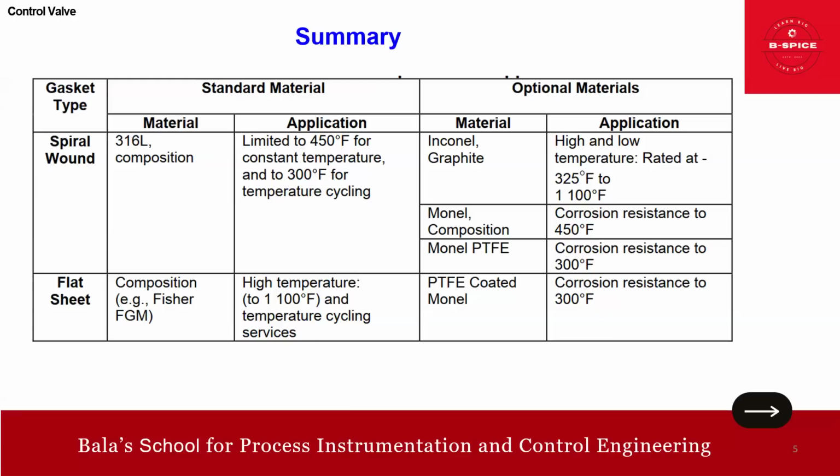But the problem is they will not provide the required corrosion resistance. So options such as PTFE coated with Monel provide corrosion resistance up to 300 degrees, but again at a reduced temperature rating. So this is the summary of all these gaskets, their applications, material composition and temperature,